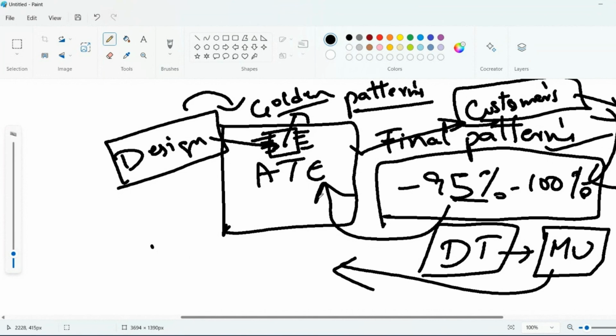Our patterns are for the entire SoC. Each module of your entire SoC is tested. Your patterns have the test vectors, the stimuli or response captured for every module inside your SoC. So all these patterns will help you diagnose each individual component post manufacturing.